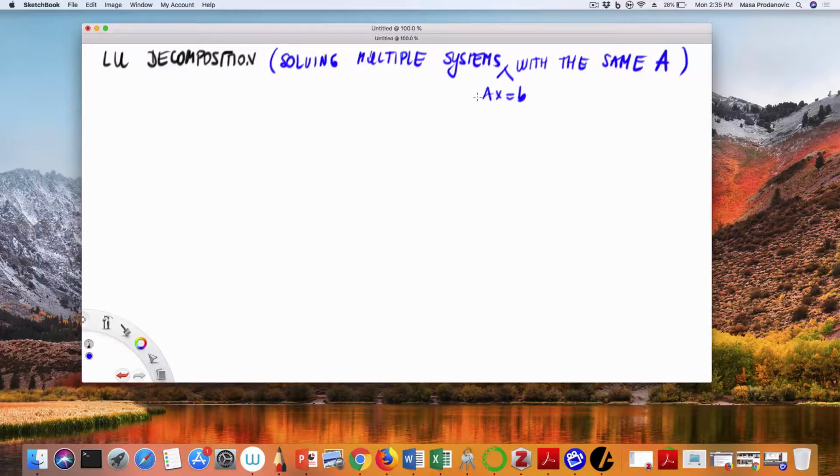So first thing that we can do is simply be smarter, okay? If I'm going to solve a lot of systems, and often, so this previous problem, that tridiagonal system that we got, if I wanted to resolve that problem with different temperatures as the boundary conditions, my main A, that tridiagonal matrix, would remain the same. The only thing that would change would be that right-hand side, that B.